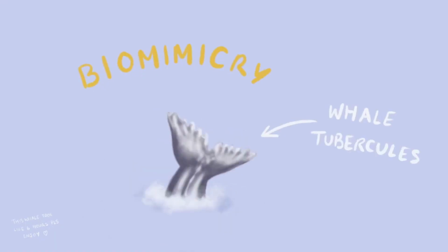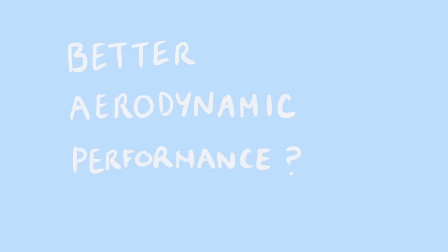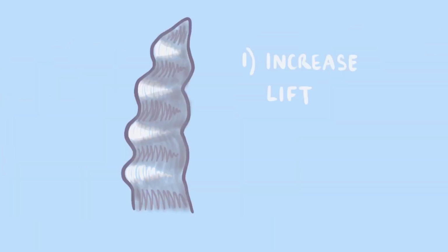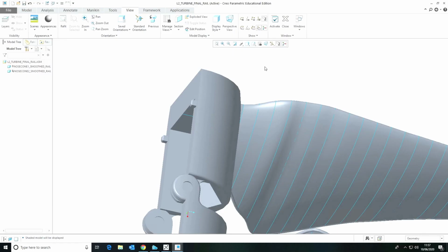Designing the turbine, we explored biomimicry to improve the performance. We found that research in a combination of fluid dynamics and biomechanics explored how and why tubercles found on whale fins made rotary devices more efficient. CFD showed that these tubercles can increase lift and decrease drag at the same time. The tubercles focus the flow between the bumps via complementary vortices, creating high lift regions where the flow stays attached. These regions have significantly higher stall angles. Unlike other wings, which may stall violently and potentially damage the machines they're employed on, tubercle wings will always stall gradually. Therefore, in our design, we have made use of this technique and incorporated it in the transition of the two chosen airfoils to reduce the chance of sudden stall.